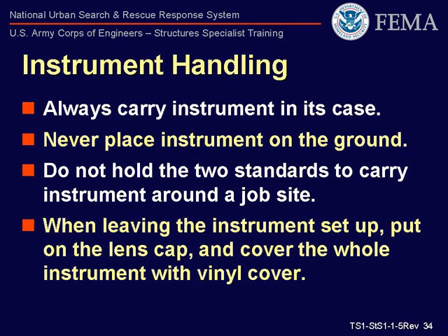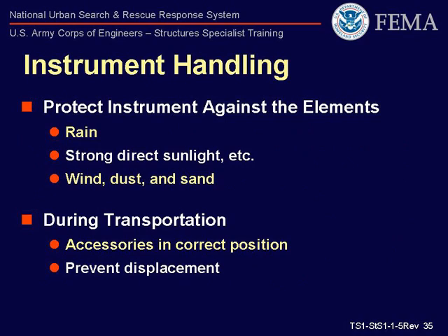Always carry the instrument in its case. Never place the instrument on the ground. Do not hold the two standards to carry the instrument around a job site. When leaving the instrument set up, place the lens cap on and cover the entire instrument with the vinyl cover. This will help protect the instrument from the elements such as rain, wind, which could bring dust and debris. It is also important to transport the instrument in its case with all appropriate measures taken to properly store all loose items.